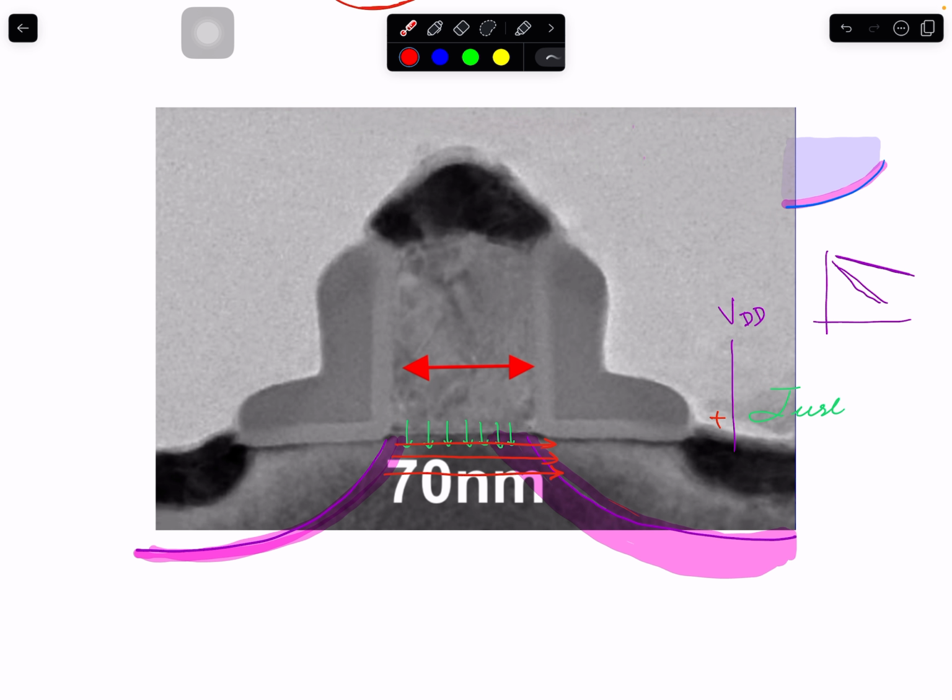Now what this dragging does is affect the threshold that we had. Unless we apply a gate voltage, now you don't need that much gate voltage. See, the strong inversion doesn't happen abruptly, it starts happening gradually. So a little bit of gate voltage here will create some electrons, a channel, an n-type material here, that this strong voltage will start pulling all the way here.